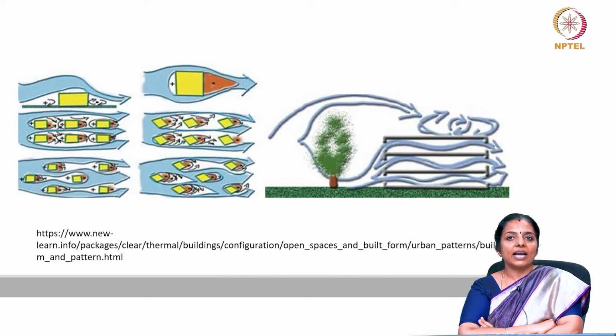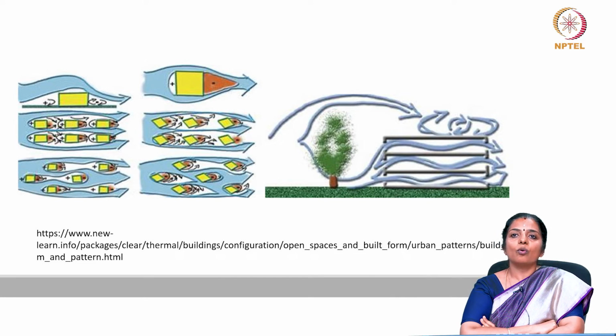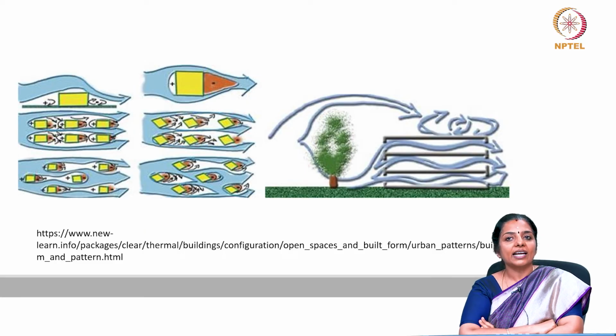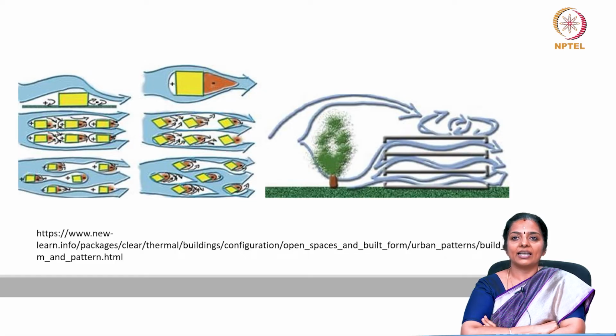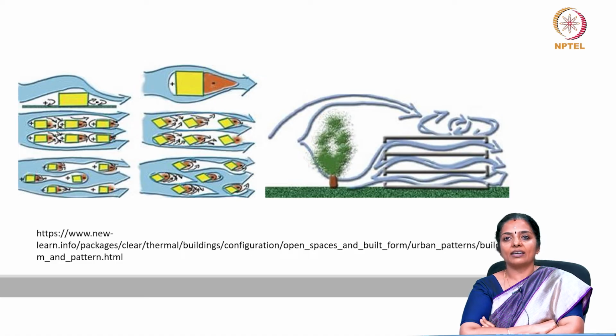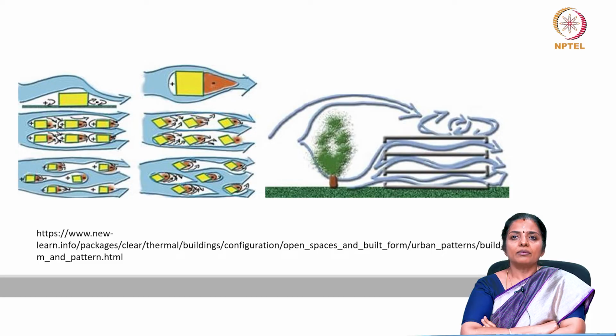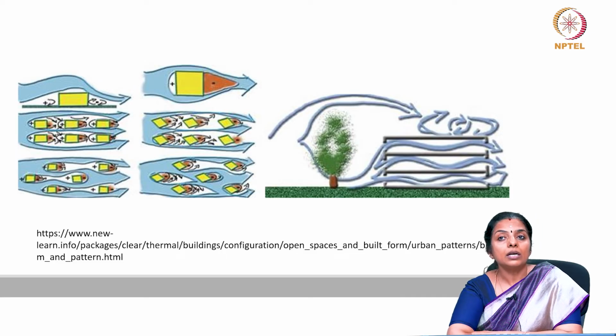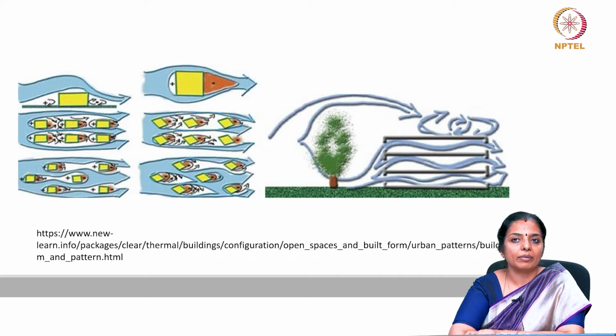The regional air currents flow mainly over the top of the buildings, while in between the buildings a secondary airflow pattern is created as a result of the friction between the upper air currents and the building. This may be desirable in certain climatic conditions like cold winters or hot summers when winds are to be avoided, but undesirable in warm humid climate when ventilation is required.